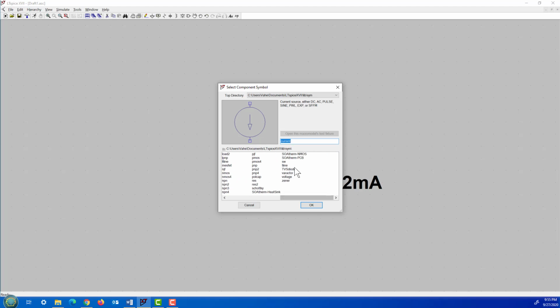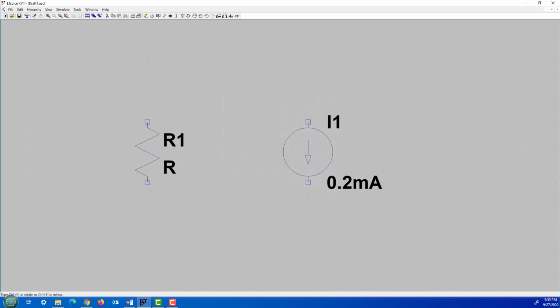Here's a resistor. I'll tell you 3 ways of entering a resistor. Here's a resistor. You okay it, and you put it here, maybe make this 4.7 kilo ohms, right? 4.7 K, right? So this is 4,700 ohms. There you go. Okay, another way to put in a resistor is go right here. There's a little resistor symbol. Click that, and you have a resistor again. Let me rotate that. Control R to rotate, right? Control R to rotate. I'll put it down and right click to not keep entering the same resistors again.